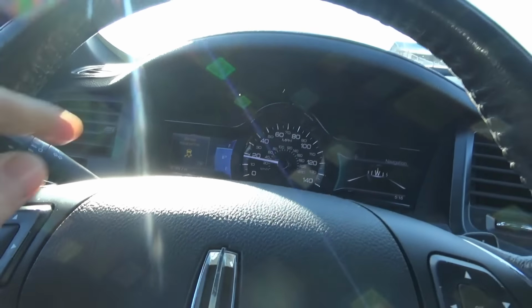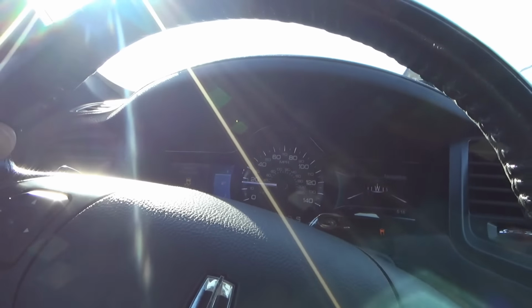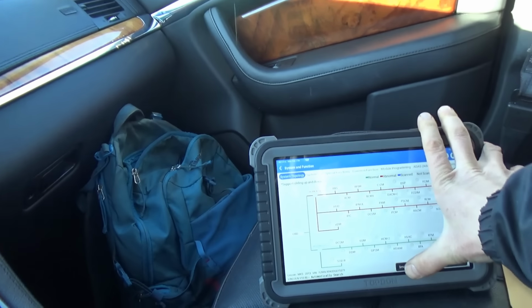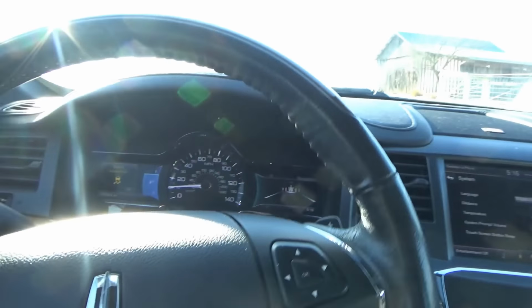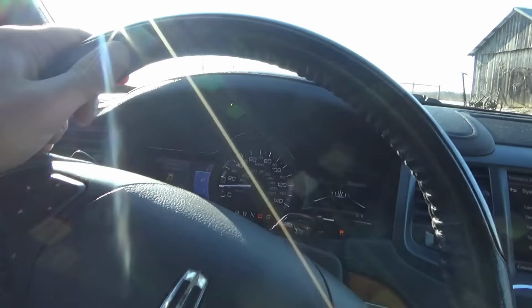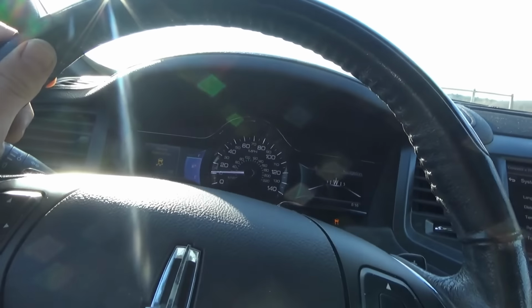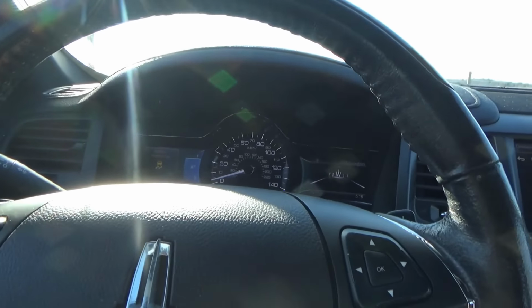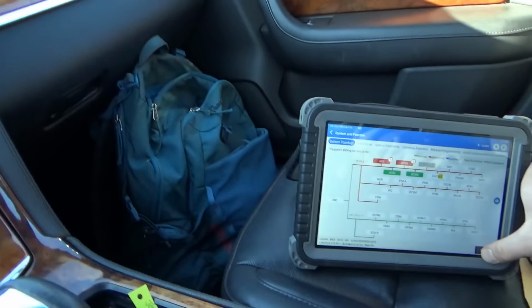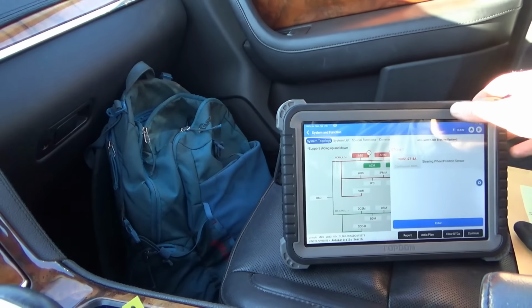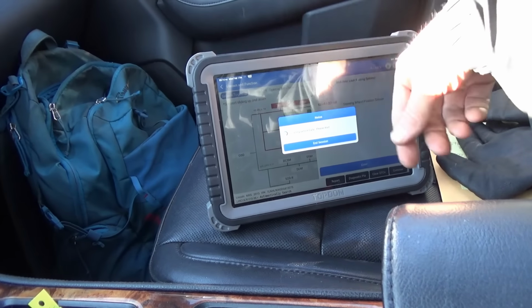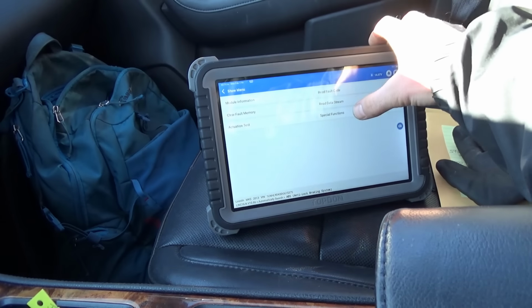Just fine. So I'm driving on the rough road here. I took a turn. Bam! Service advanced track again. So let's rescan the whole car again. That fault went away for a little while when we were cruising. Is it going to say steering angle fault? Steering wheel position sensor. Let's read the position sensor while we're driving on the bumps.